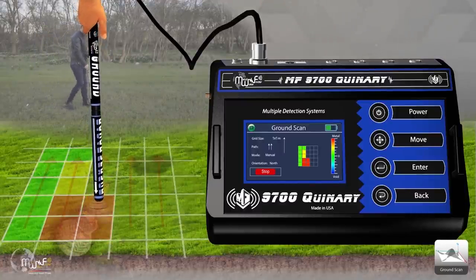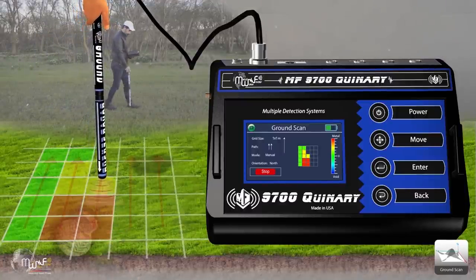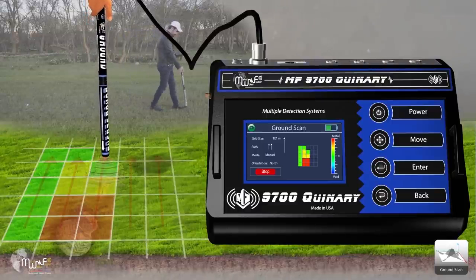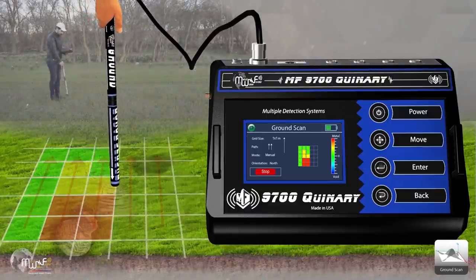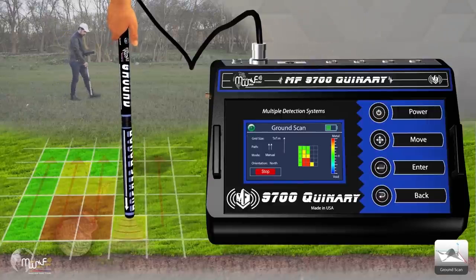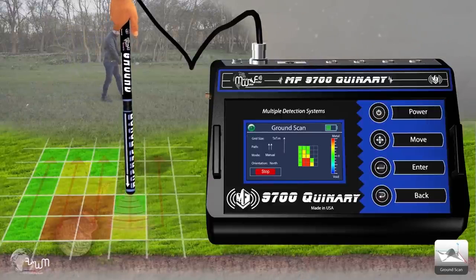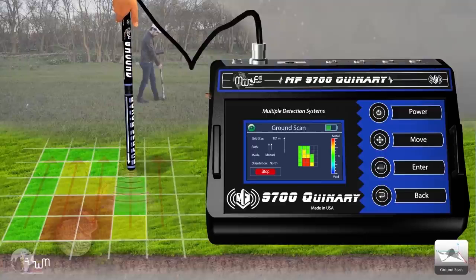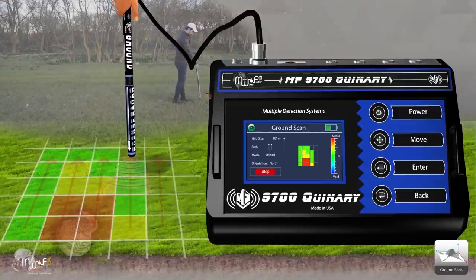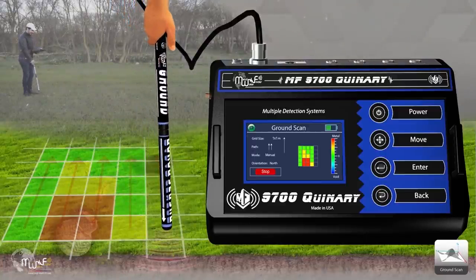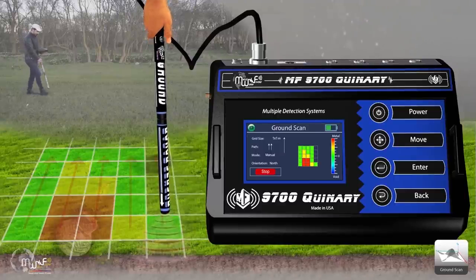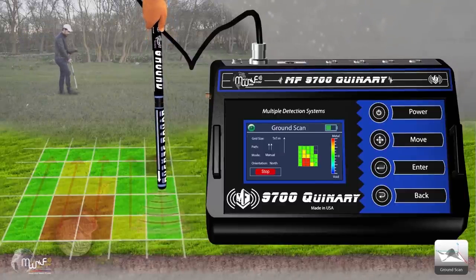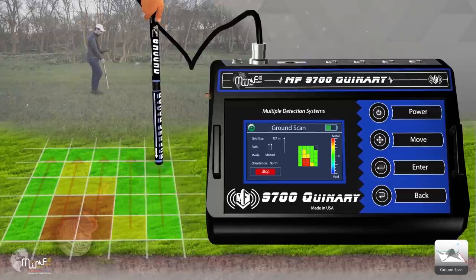Ground scanning is done by taking a scan point every 20 cm, depending on the size of the search grid previously chosen, until finishing scanning the area to be checked. Important note: when scanning the area, the direction of the sensor must be preserved and should not be changed, meaning it should not be turned left or right.